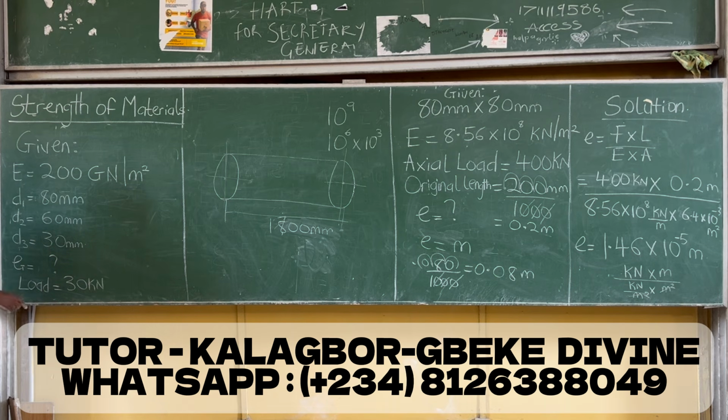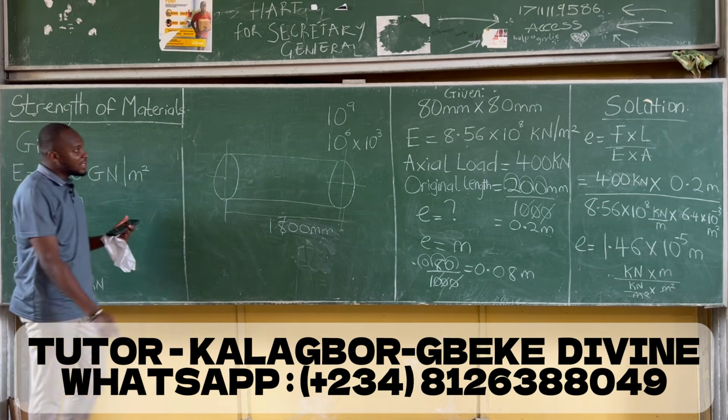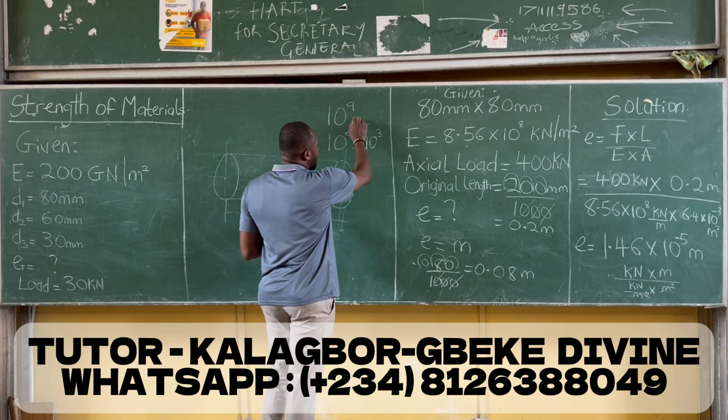So now we're looking at the tensile load and the Young's modulus. What is the difference? This one is in giga, this one is in kilo, so they cannot cancel out, right? We either convert this one to giga or convert this one to kilo. So now let's go back to this thing I wrote here. This is giga, right?